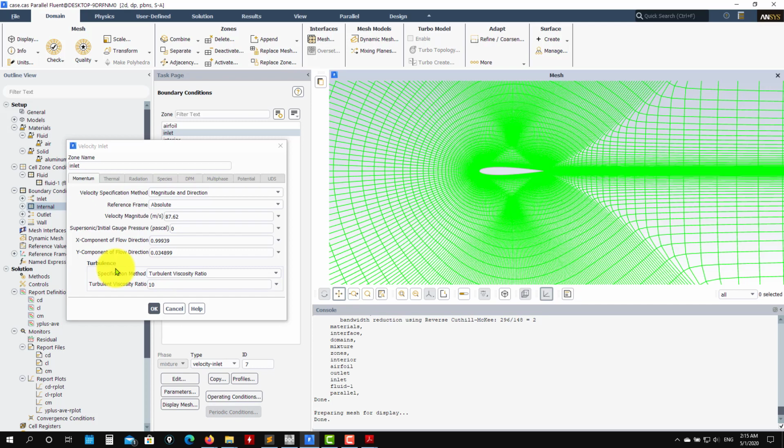and then we give the specification of the boundary condition for the turbulence model. So in this case, we're using Spalart-Allmaras, which only takes the modified turbulent viscosity. So we saw the theory, something between 1 and 10. So let's use 5 here. Okay, it's up to you.